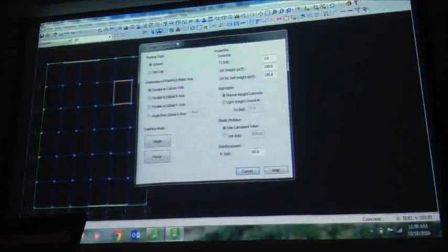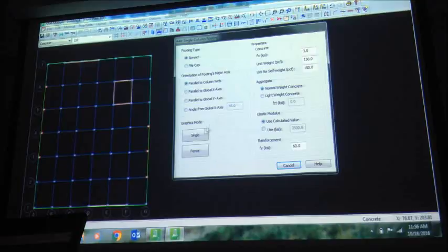Now I will go to the first floor. Loadings are changed. Only thing I'm going to do is add foundations. So go layout, foundations. Each of these gravity columns will have a single spread footing. So single column footing, add. I'm just going to use the same thing. Use single. Click on that. It will show a column foundation.